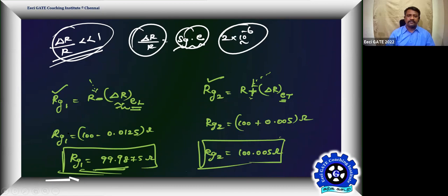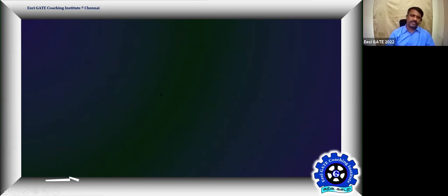Now you should think of transduction. So now we know how to convert force into strain. Straight away, the load cell plays a role. That's the primary sensing element. And strain into what? Change in resistance. Who plays a role? Strain gauges are playing the role. Correct? Easy? Yes, sir.